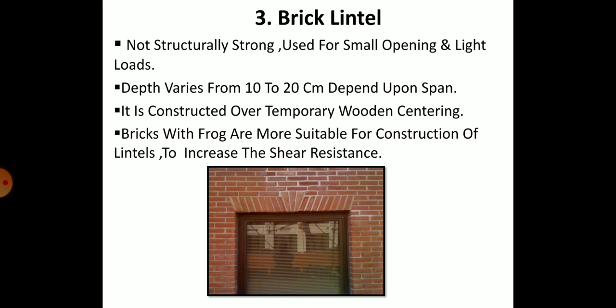Also, bricks with frogs are more suitable for the construction of lintels, since the frogs form joggles when bonded, which increases the shear resistance of the end joint. Such a lintel is called a joggled brick lintel.